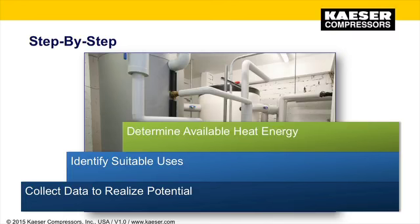Step 3. Determine available heat energy. You look at the compressor parameters, the measured loading times of the compressors, the working hours per year, and the type, usage, and cost of heating energy.